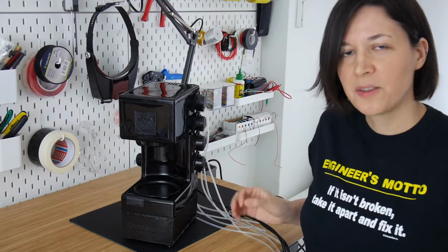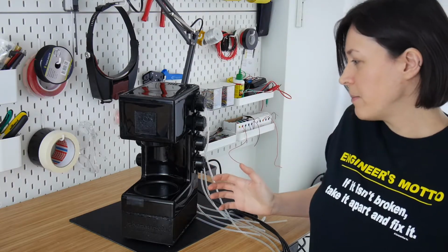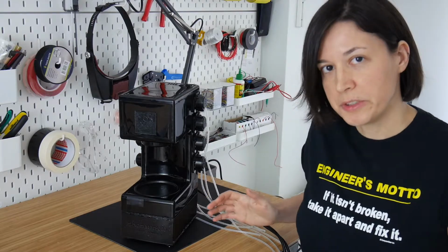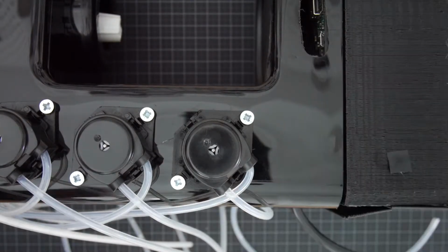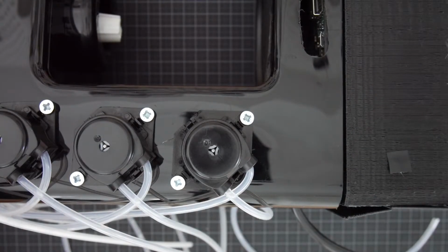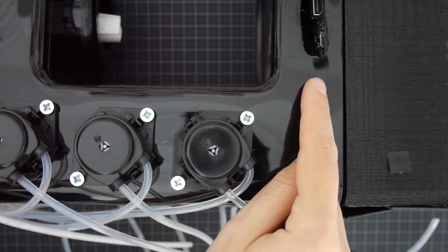So it works. I can order through the web interface or the Google Assistant. But I'm having some issues at the moment. While connecting to Raspberry Pi through SSH, I could see my connection goes down once in a while. So I think the problem is that the Raspberry Pi didn't have enough power.